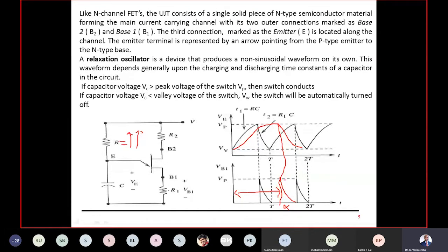That is depending upon the time constant of my RC elements. This is actually my variable resistance. Once I set the resistance to a particular value, maybe 10 ohms or 20 ohms, the respective firing angle will be fixed, such that every 45 degrees my pulses will be given to the SCR and the SCR will be turned on.